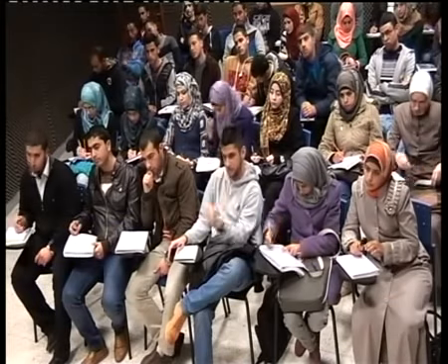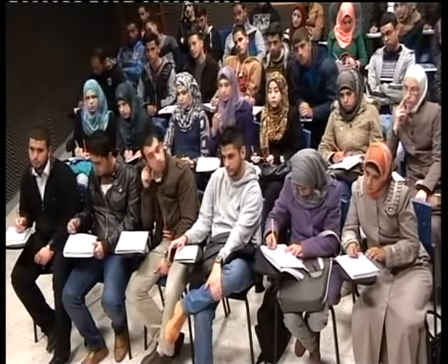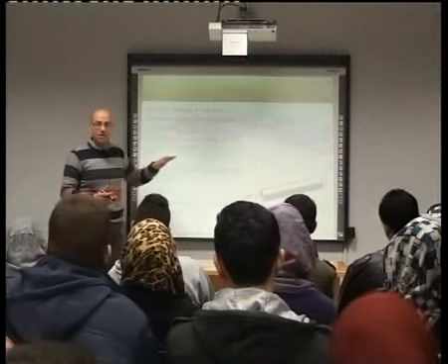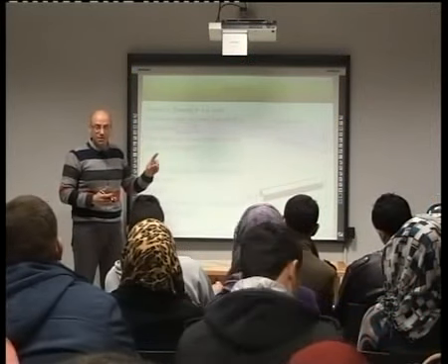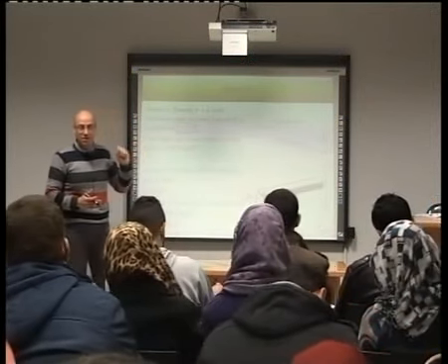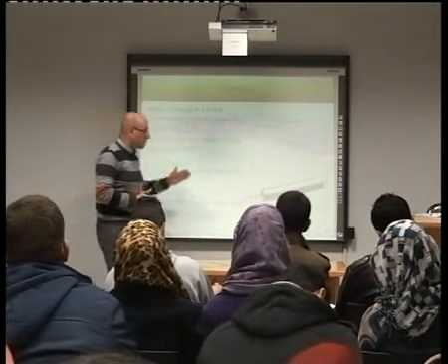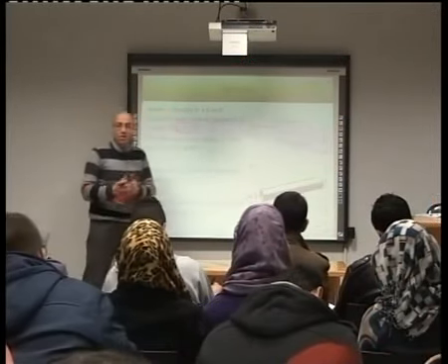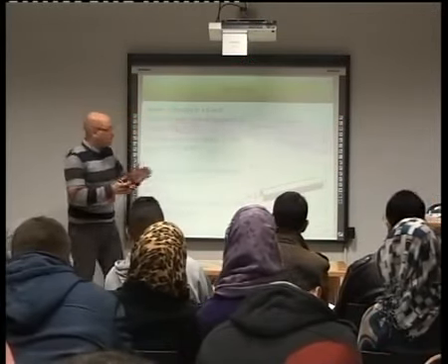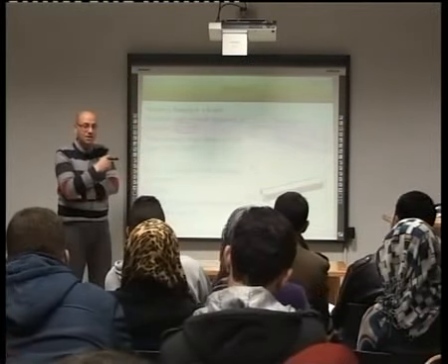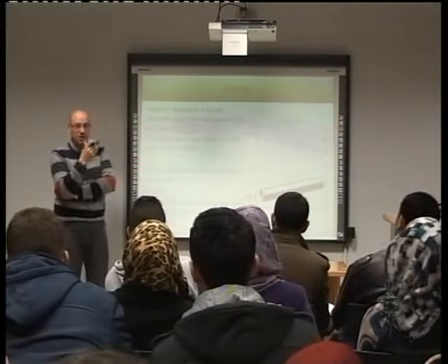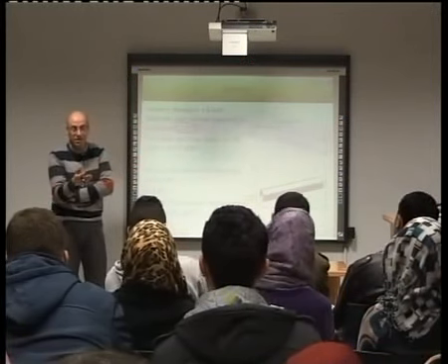As you move, for example, 1 foot in the horizontal direction, you will go up 0.1 in the vertical direction. That means if this is a 1 kilometer length of a pipe, what will be the end elevation or end difference? 10% from that. That means 100 meters.